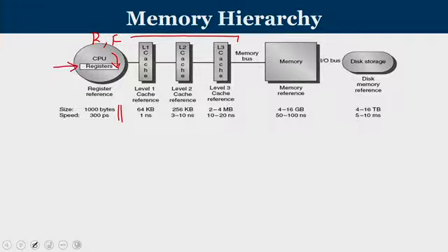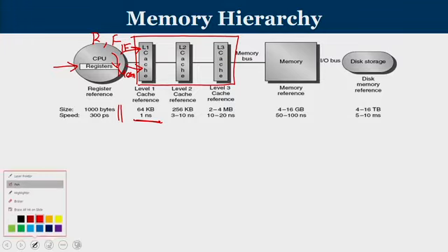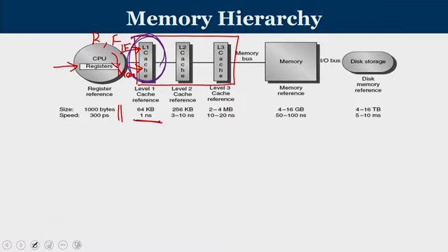And then we have multiple levels of cache memories. This is what we are going to learn today. And these cache memories are relatively very fast. The L1 cache, which is the closest to the processor, will be in the order of kilobytes, and accessing it would be at the same order as that of accessing any other stage of an instruction pipeline. So during your instruction fetch stage, you are going to take something from L1 cache, and your mem stage also you are going to access something from the L1 cache. So your instruction pipeline is interacting with this L1 cache alone. This is the cache where the instruction cache is directly interacting.